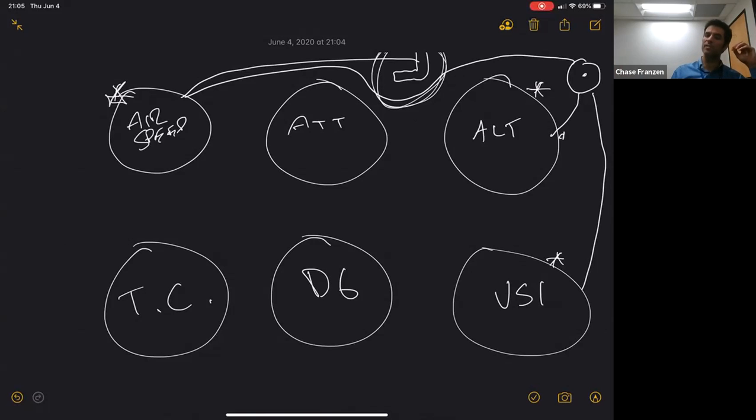And that's why the airspeed indicator can only indicate indicated airspeed. That sounds like a lot of indicated, but why can't the airspeed indicator show us the true airspeed or the ground speed or something like that? Well, it can't, because it's really not measuring airspeed at all. It's measuring air molecules. And as we climb in elevation and altitude, there are far fewer air molecules at 10,000 feet than at 1,000 feet.